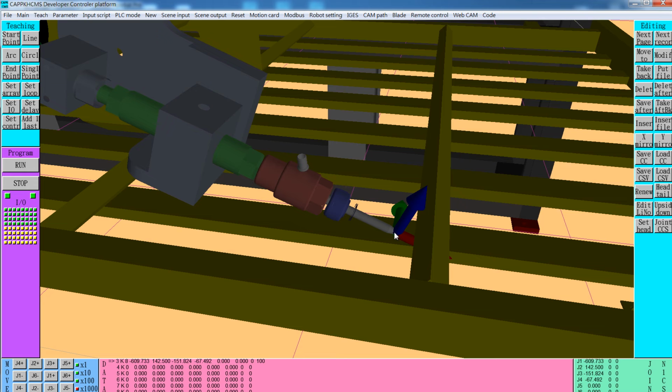Then we have to add something in front and at the rear to let the tool lower vertically and incline thrust in. How to insert something in front? Change the position to the first line, and then insert one line in the first line.